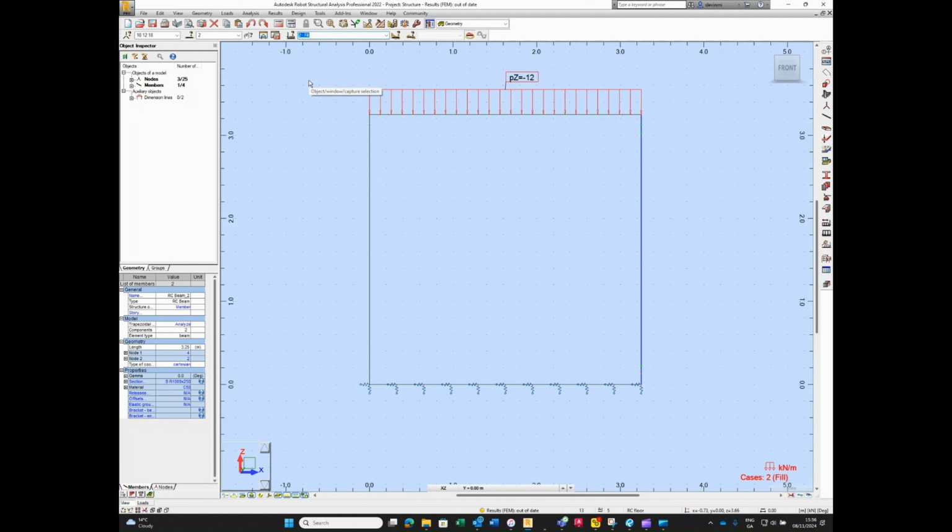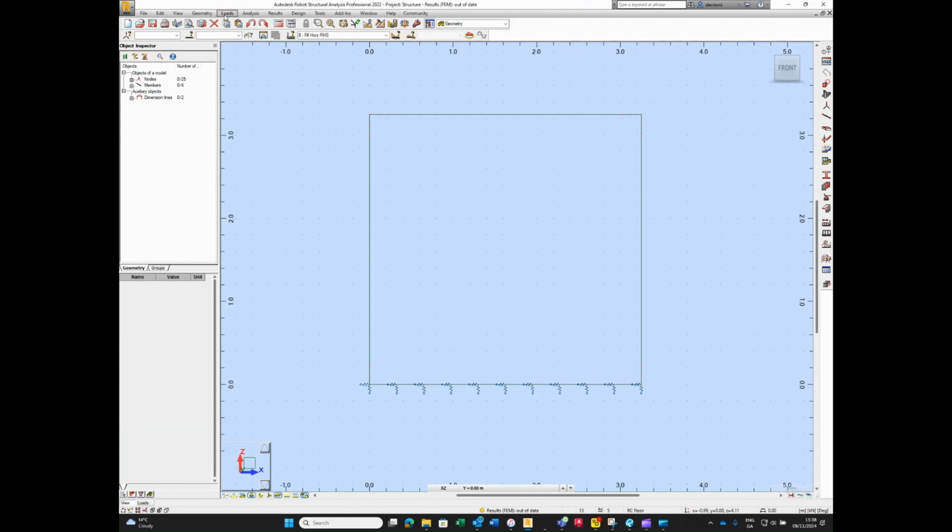Okay, so that's just some typical loads that will be on a culvert. There's obviously more, depending, you're going to have your tractions, your accelerations, different bits and pieces, and then we'll just do one simple load combination here. Loads, we go manual combinations. We'll just do our SLS first.